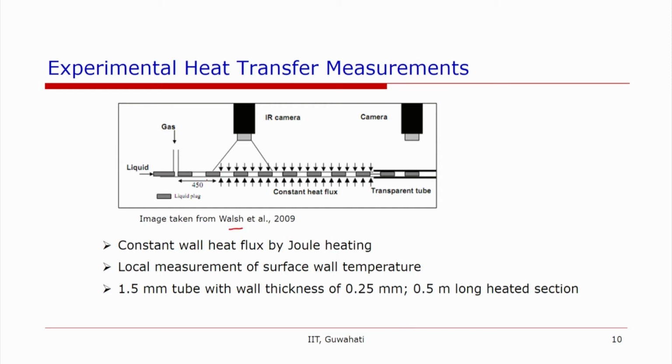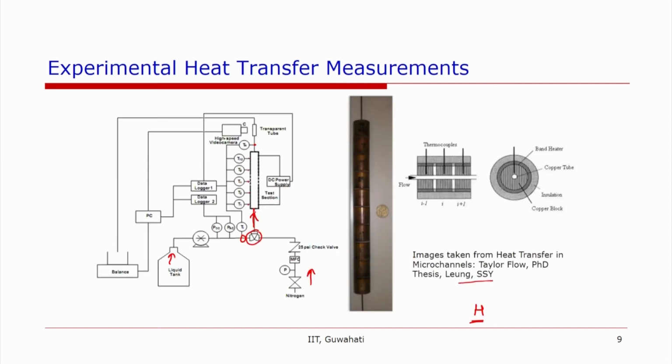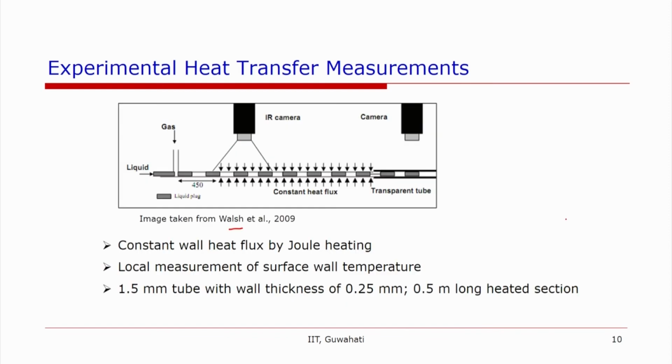It is a similar test section, and they have also made sure that the flow is hydrodynamically fully developed, and then heat is applied by Joule heating, and the local measurement of surface wall temperature is being done, probably using an IR camera. They have taken different tube cross sections, wall thicknesses, and lengths of the heated section. They are also looking at the fluid behavior, the flow regimes at the exit.